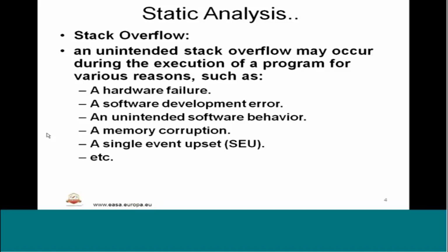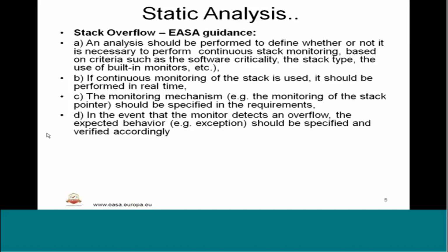As per the ISA guidelines, stack overflow needs to be taken care of in such a way that an analysis is performed to define whether or not it is necessary to perform continuous stack monitoring. That means whether it is part of the built-in program or not. If continuous monitoring of the stack is used, it should be performed in real time when the program is running, with a specified task allocated for it, a tiny program or a tiny slice of time.